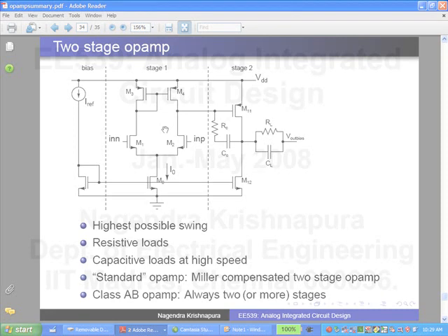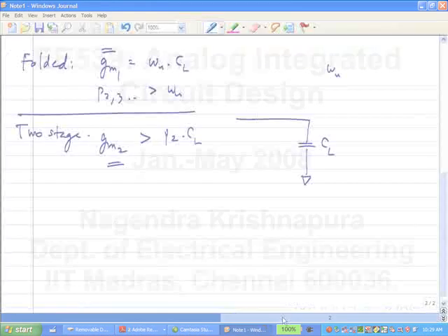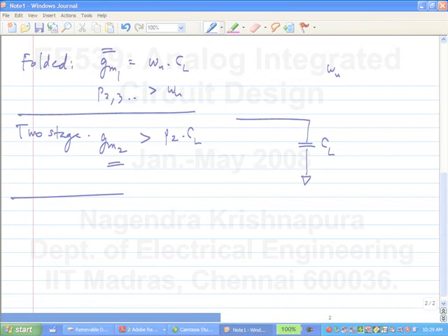Output? No. The question is, when you use an op-amp as a voltage controlled voltage source, the output resistance should be very low. So how will any of this help? All of these have high output resistance.